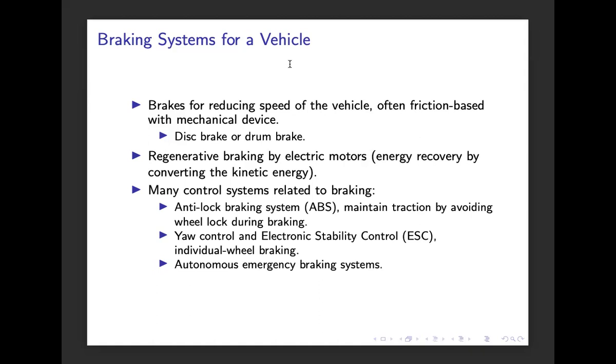But also, if we have electric motors, we sometimes need to model regenerative braking. That is, we use the electric motor to decrease the velocity of the vehicle as well. So we somehow turn the motor into reverse and make it a generator to convert the kinetic energy of the vehicle into something that we can either store in a battery or use directly in some other form of energy.